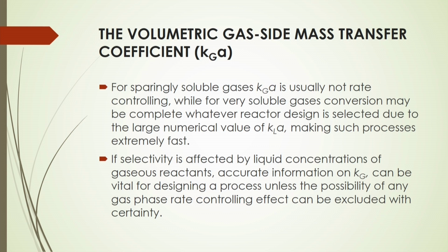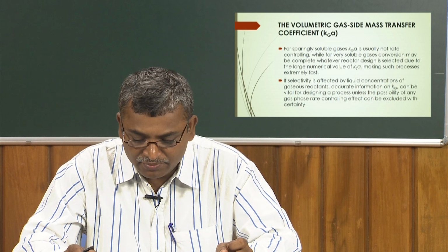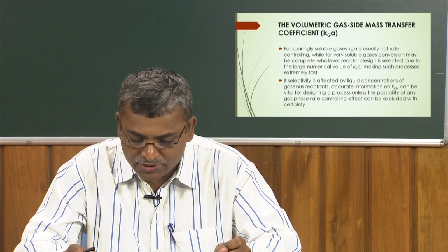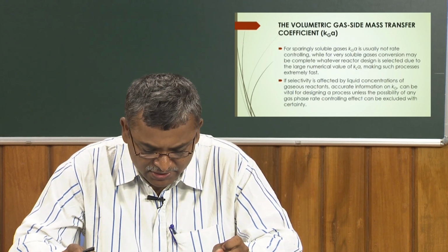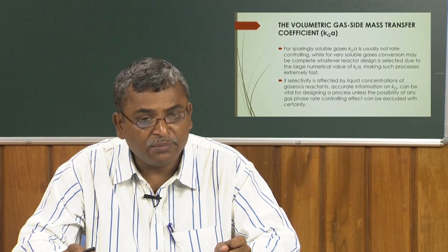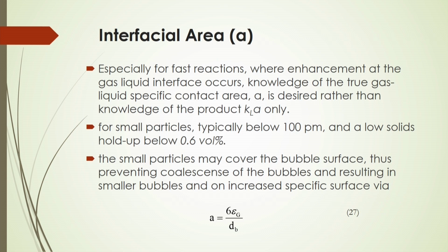In that case selectivity is affected by the liquid concentrations of gaseous reactants, and accurate information on the gas mass transfer coefficient can be vital for the design of the processes. Of course, any possibility of a gas phase rate controlling effect can be excluded with certain phenomena.